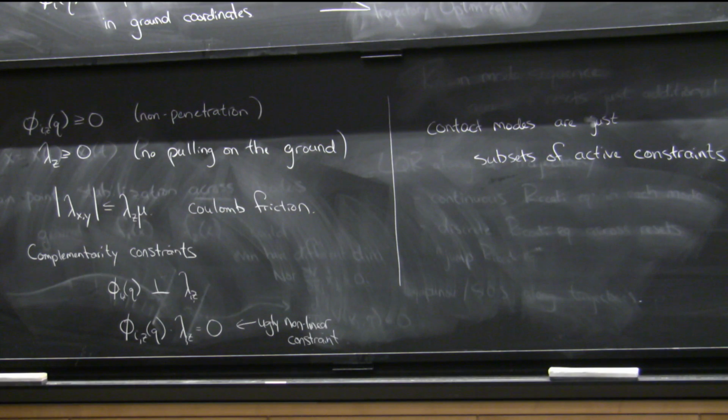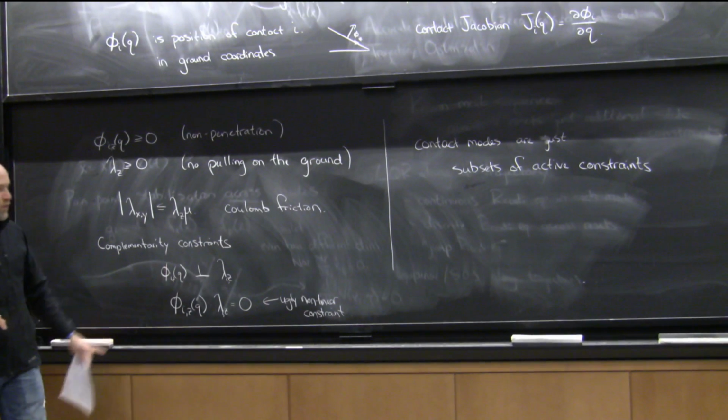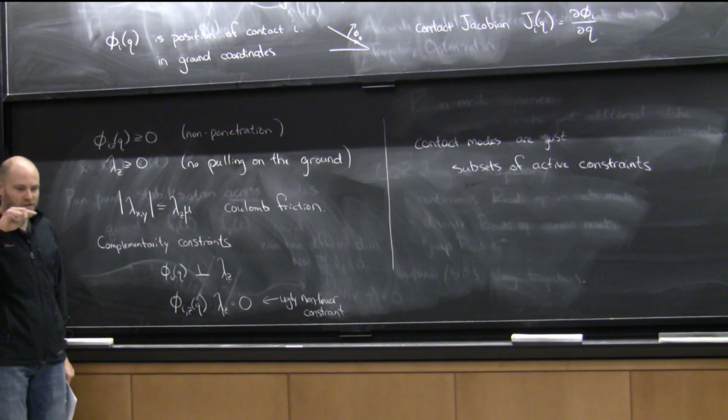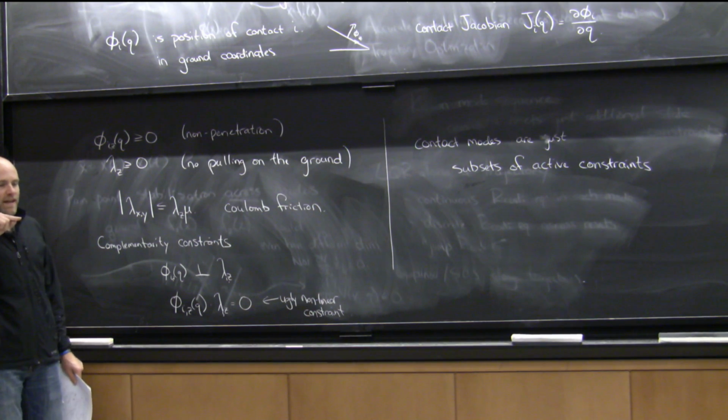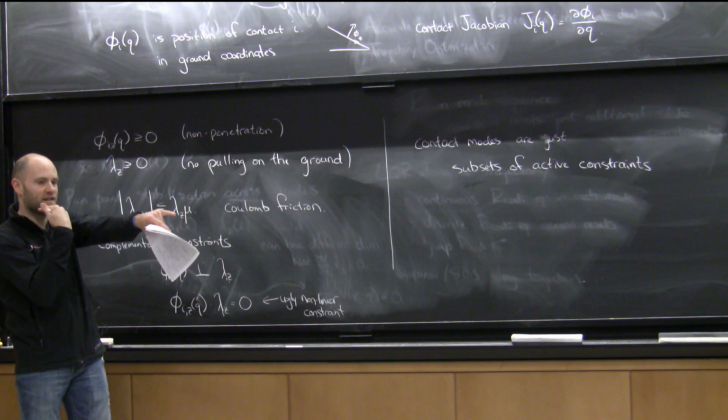It's actually even worse than that, because this is just in the sticking regime. If you have friction and sliding friction, then you have additional constraints. The standard way to model sliding friction is with maximal dissipation. Basically, if I am moving at all, then my contact force is the force that will take the most energy out of the system instantaneously.